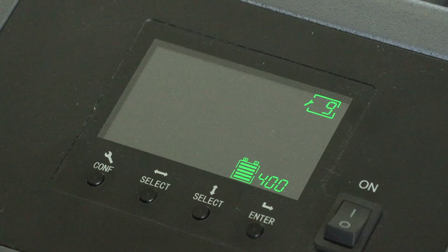Menu 9 sets your battery capacity setting. This is strictly for your display. Changing this can change what percentage is shown for your battery capacity based off the ampere hour capacity of your battery. You may find that setting this higher than the actual ampere hour of your battery can make it more accurate. For the bank, you do not need to change the setting.